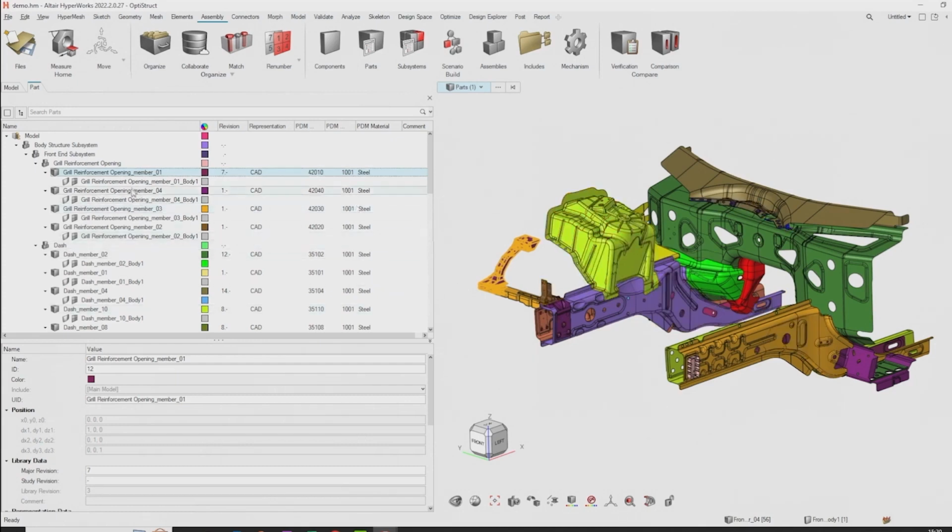Even on the property creation, we extract the thickness from the geometry as part of our batch meshing process. So there should be no manual creation of properties or materials anymore. We do that for you, and we automatically create them with the right names, IDs, and thicknesses.